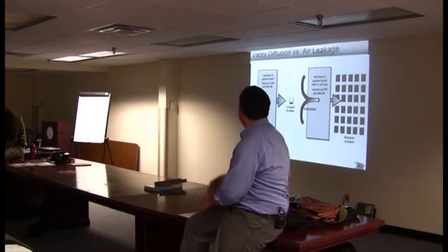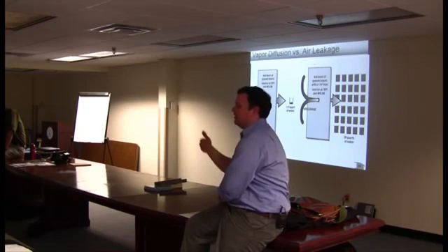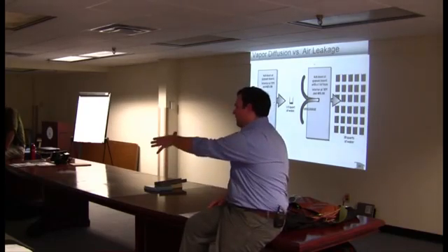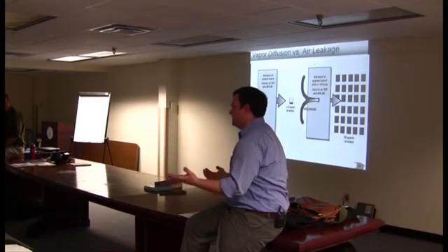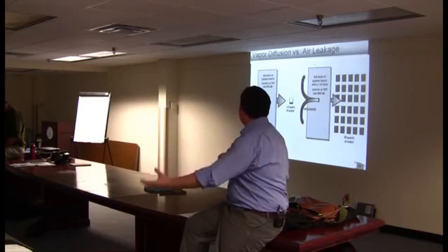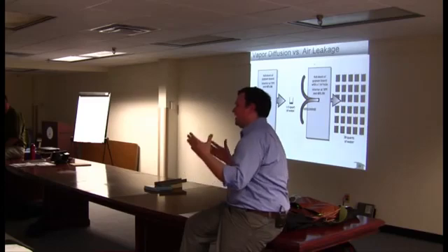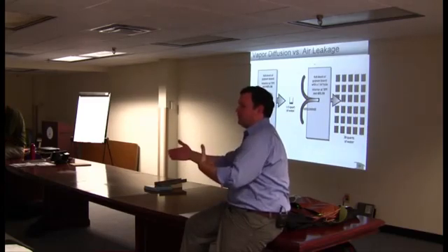So what we're looking at here is basically a demonstration of the amount of moisture that can move into a building via diffusion or via air leakage. Over on the left, we've got a graphic of an 8x4 sheet of gypsum board. This is over a heating season. We're looking at roughly 70 degrees interior, 40% relative humidity, and the amount of diffusion that is going to occur through that piece of wall board.